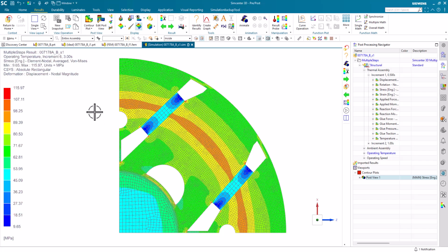This is the peak temperature load, and then we have the last subcase, which is adding the rotation, so increasing the rotational velocity. And the contours pretty much aren't changing, but again, the numbers on the color bar were changing as well. So now I want to create a result probe that will compute a stress margin.